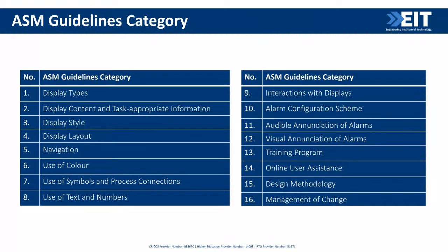Interaction with displays or alarm configuration schemes, audible annunciation of alarms, visual annunciation of alarms, training program and online user assistance, design methodology that can be used to build SCADA systems or displays, and the management of SIM. So the critical point to be taken here is that the implementation of the individual guideline in itself will not guarantee an improved effective operations practice, but together all of these guidelines will form an integrated program that will lead to quite a lot of improvement.